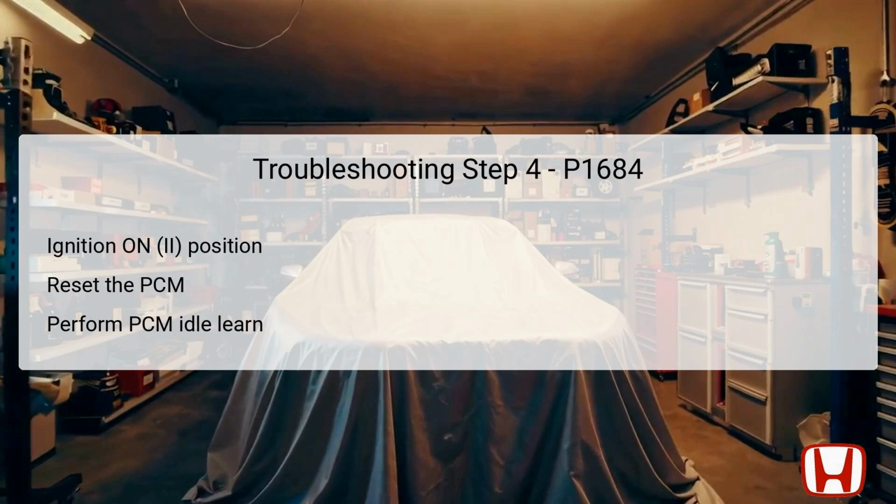Following the reset, the technician must perform the PCM idle learn procedure, which allows the PCM to adapt to the new or clean throttle body settings. This process ensures optimal performance by recalibrating the engine's idle speed and response characteristics, preparing it for safe operation.